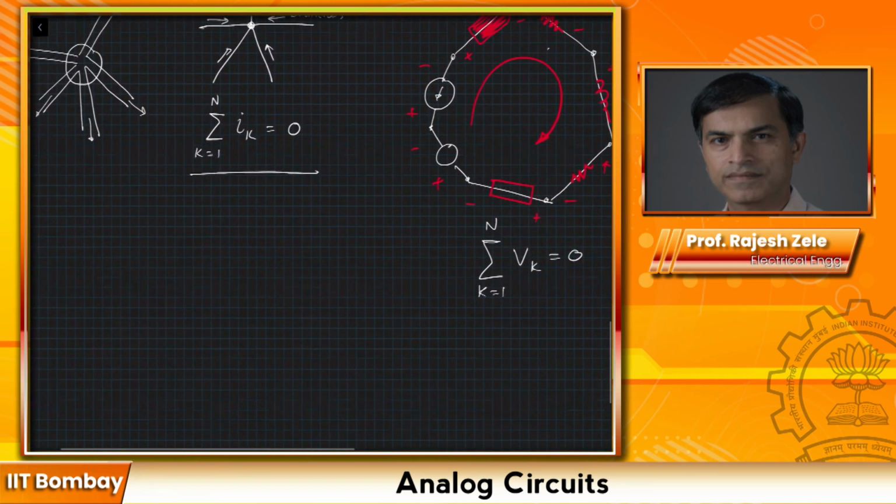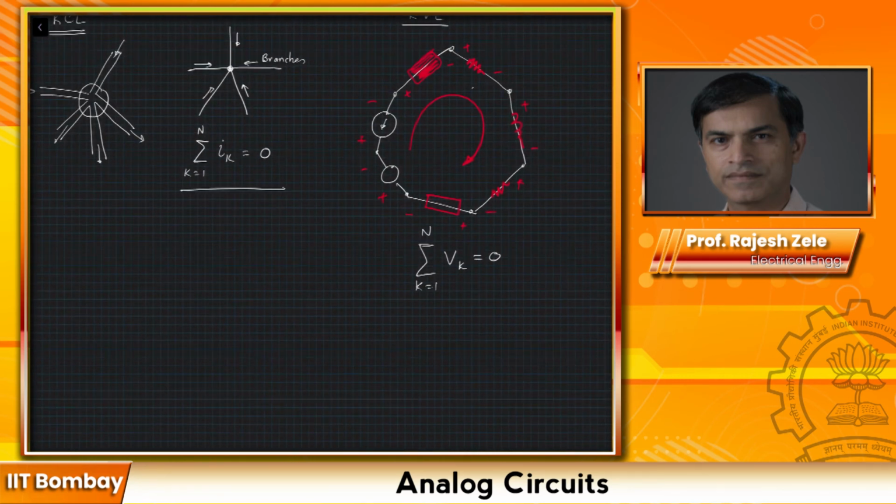The next popular law that we use in circuits is Ohm's law. In Ohm's law, let's say there is a resistor and there is a voltage across the resistor VR, and there is a current flowing through the resistor which is IR, and the value of the resistor is R. So Ohm's law says that VR is equal to R times IR, or the value of the resistance is equal to V divided by I across the resistor.